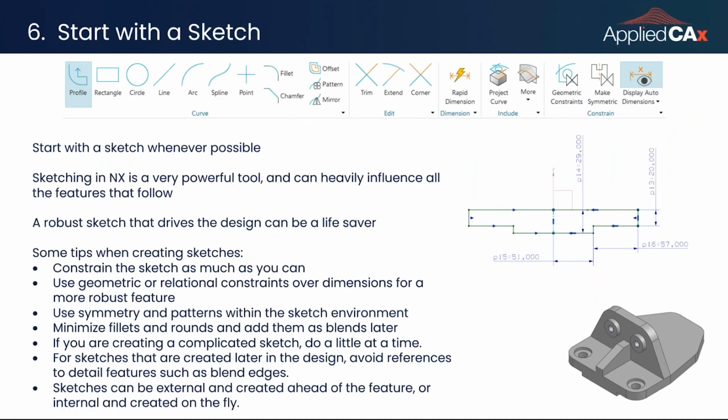However, if you don't have the ability to reuse very much and you are just starting from scratch, then you're going to want to start with a sketch. Sketching in NX is a very powerful tool. It heavily influences all the features that follow, especially if you set it up correctly. So start with a sketch whenever you can. A robust sketch that drives the design can really save you a headache downstream.